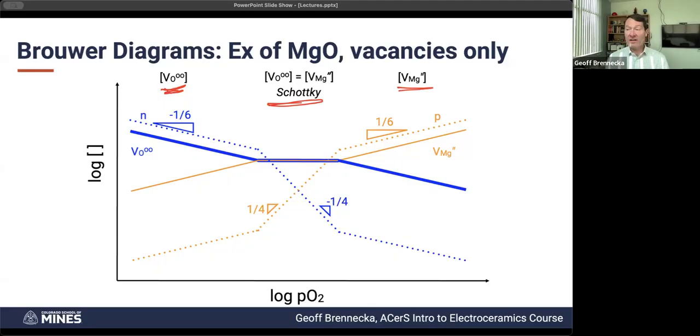But if your sample is an oxide and you get to a high enough temperature, the PO2 is going to be low because you've got argon around. And so you can still lose oxygen from your oxide sample in an inert, non-reactive environment just because that environment doesn't have oxygen. You're going to essentially boil off oxygen from your sample surface. That's why the partial pressures are the parts that matter rather than the absolute pressure.